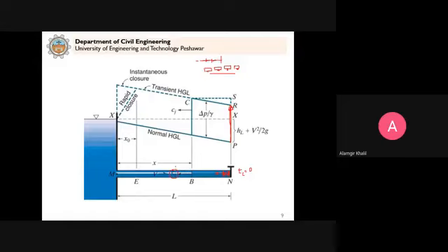So that's why Cj is written. Normally, the water was flowing with a velocity v when the valve is open. But now the effect is transferring because this is brought to rest. The effect is transferring up the pipe length. So how is the effect transferring? In the form of a pressure wave that is given by Cj. That's why we studied how to calculate this Cj, that with what velocity it will travel through the fluid. Now you understand why we studied the first topic.